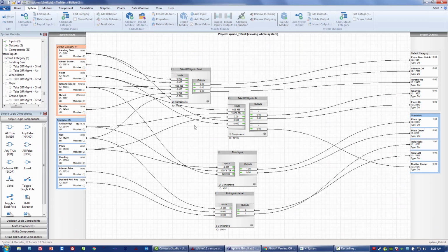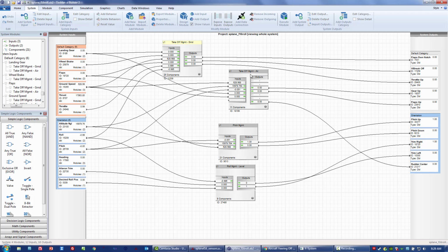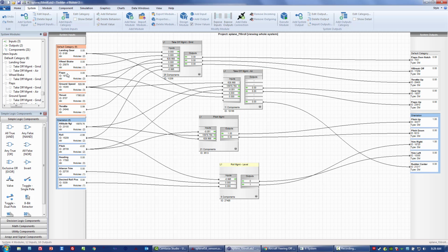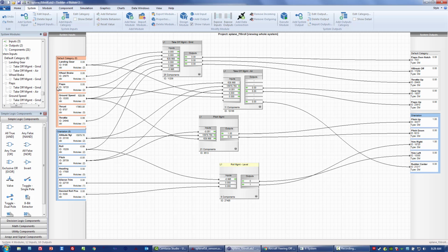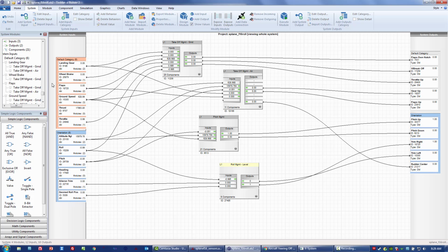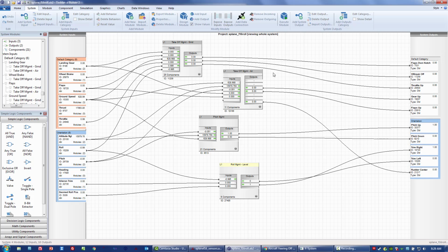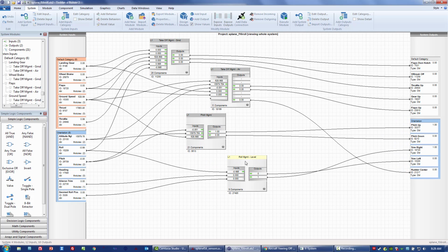The third application is TinMan AI Builder. We have 4 modules that we've created and put on the screen. The system inputs that will be received from RealTime, well actually from X-Plane via RealTime, are just a select set to do a minimal liftoff to about level flight at 15,000 feet. And then we have commands and decisions that are made by AI Builder for managing flaps, brake, throttle, landing gear, and then orientation of the aircraft as it moves through the various stages of this flight plan.